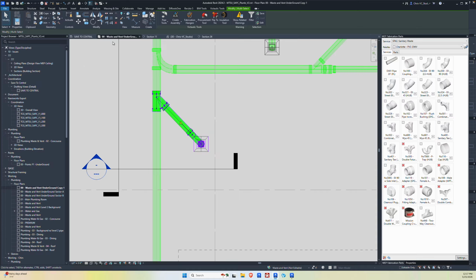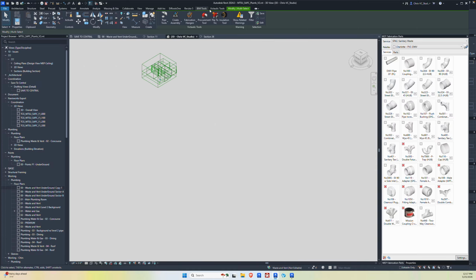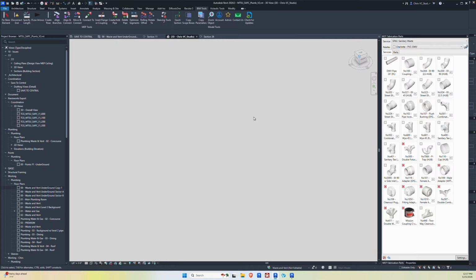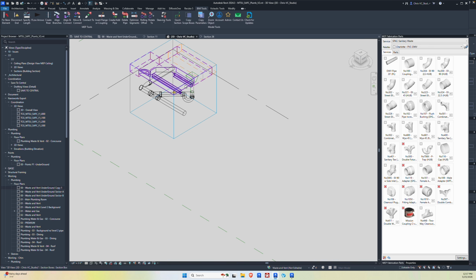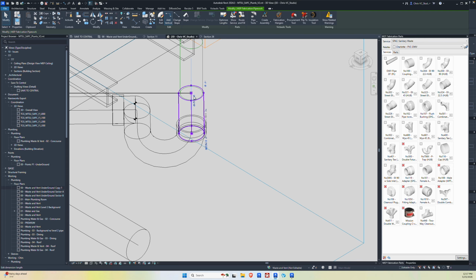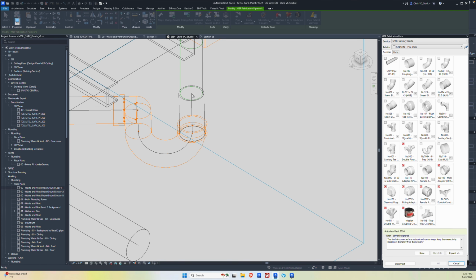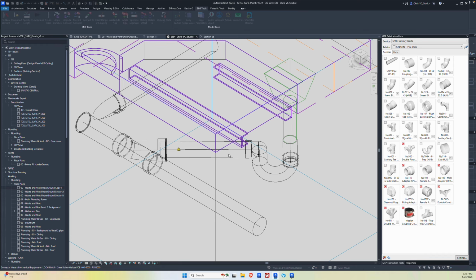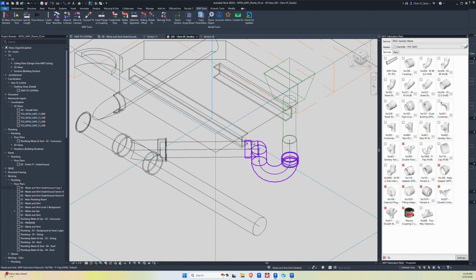And then I can find out what disconnected and go in here, use the zoom tool command, and let's flip around the other side. It's probably the P trap that got disconnected. Nope, it's the weird angled pipe there now that doesn't want to connect right. So we'll just leave that disconnected for now. And we'll come in here and we'll use the align and connect now. And we get it all to work. So that's what we have to date and how it all works.